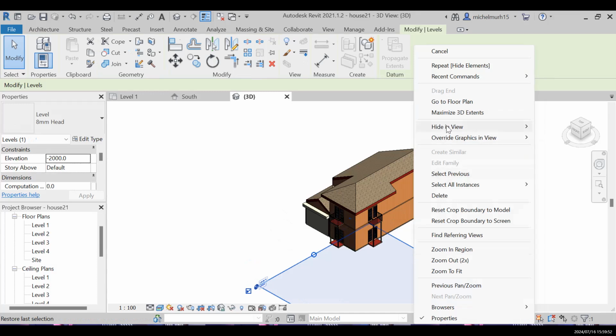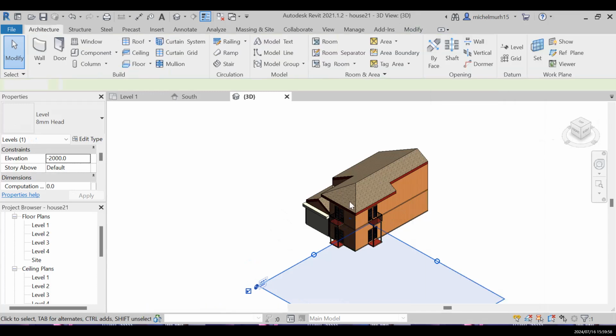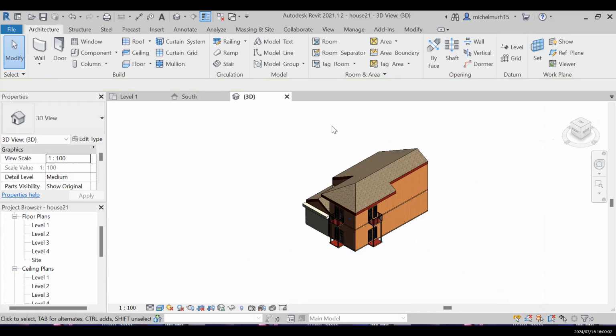And after this, what I want, okay, let me just hide the element. So what I want here, first of all, I will design my fence. I need one fence to surround my house, right? And here, I'm gonna use architecture. I'm gonna go on architecture, then click on railing. I'll click on it, and I'll take the first option.